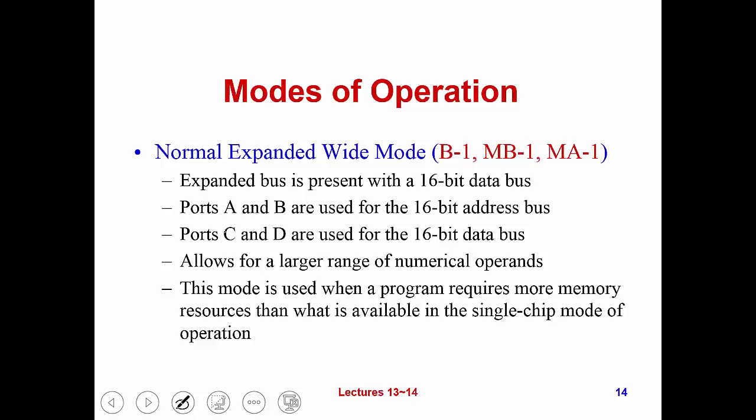But when we configure it in normal expanded wide mode, which is mode C is 1, mode B is 1, mode A is also 1, then the external bus is presented as a 16-bit data bus. Port A and B serve as 16-bit address, and port C and D serve as 16-bit data.